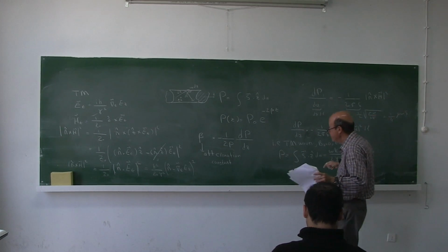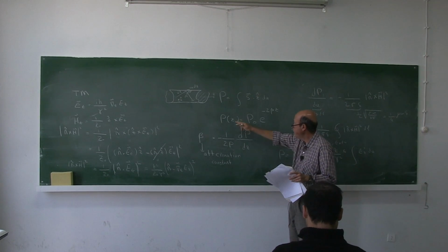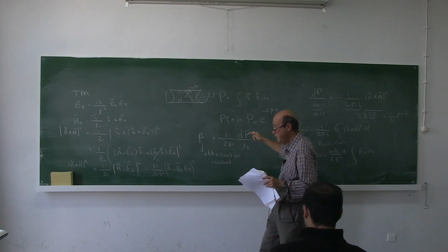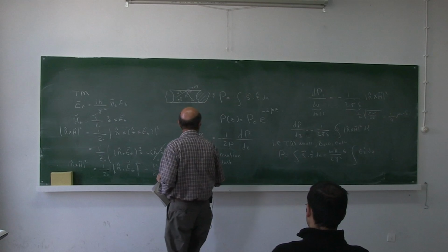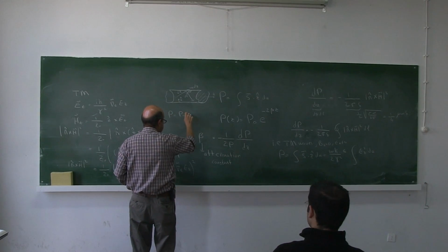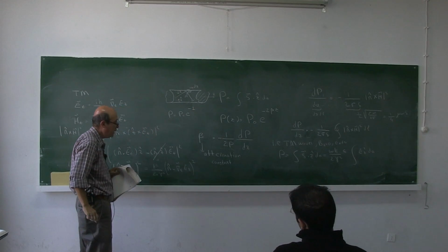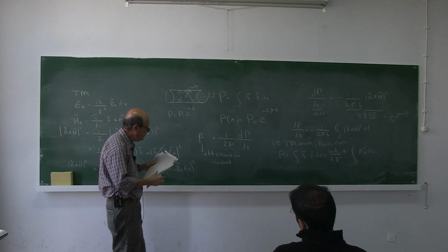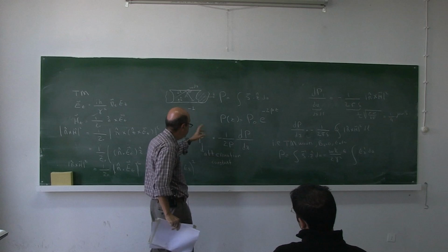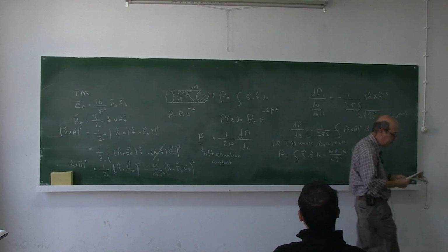So that means that in 200 and 400 meters, the transmitted power drops to the initial value times e to the minus 1. So at some distance, the initial value drops to e to the minus 1, and for a typical copper waveguide, that number is on the order of a few hundred meters.